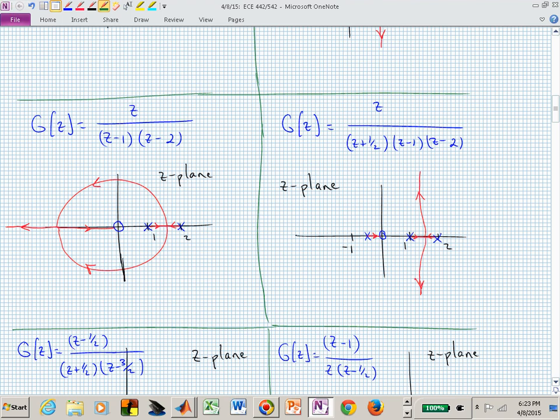And you can be very general. You could define that segment or bound it by poles and zeros. And I might say circle. I wouldn't have the root locus sketched, and I might say circle the line segment where a breakaway occurs. And I might say box the region, the real line segment, box that where a re-entry occurs.